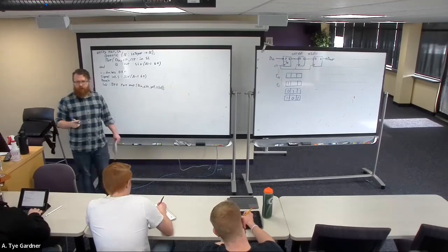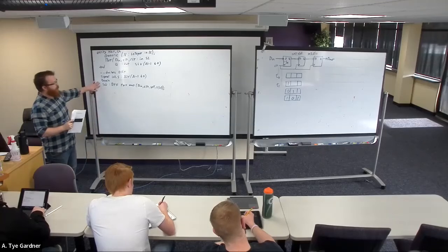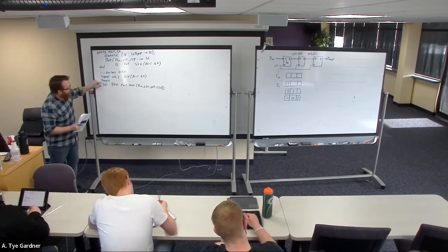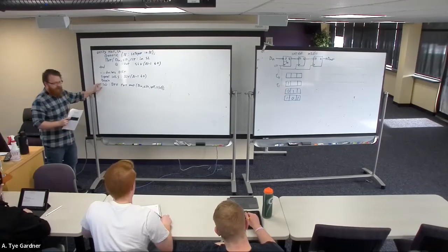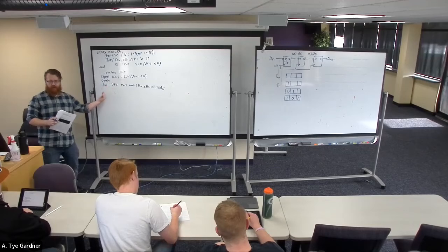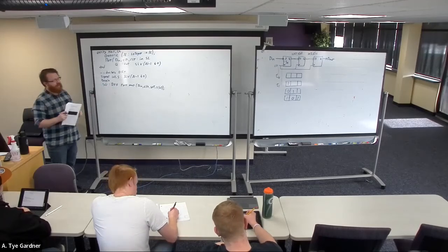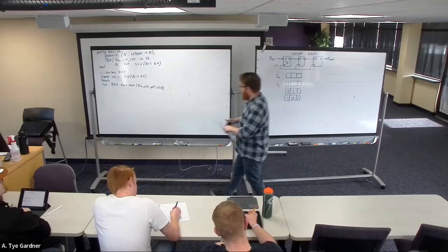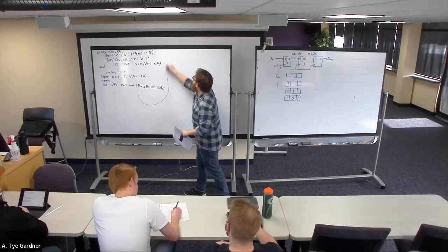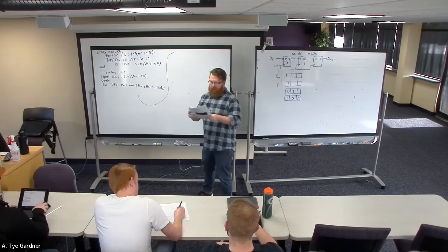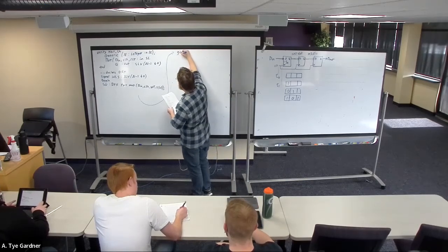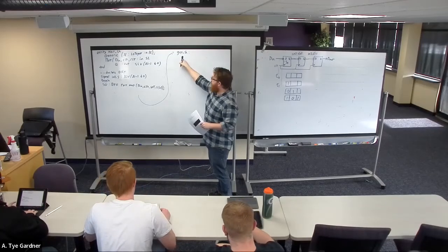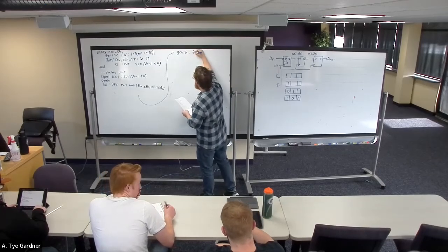So now, the current way that we would do this, if I were to finish this design, is I would sit and write S0, S1, S2, and I would connect int S to the input and int S0. But it turns out that's actually really kind of awful and tedious to do. So I'm going to start a new line so the people in back can see. So we're just going to come down from here. And there's a new thing. I'm going to use something called a generate statement. This is just the name that we're going to call gen shift, and it's going to look like a for loop.